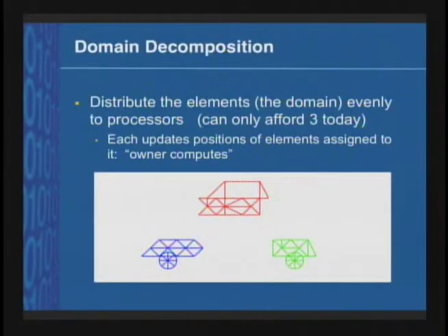So for example, here's what it would look like. In this case, I've got a very low budget. I've got 3 processors, and what I do is called domain decomposition. I break up the car into pieces. You could ask, how do I decide the pieces? It turns out there's a whole bunch of tools that do that. You actually learn techniques like space filling curves or ham sandwich theorems and so on that do it. So there are techniques for doing that, and you have to learn the appropriate technique for your discipline.